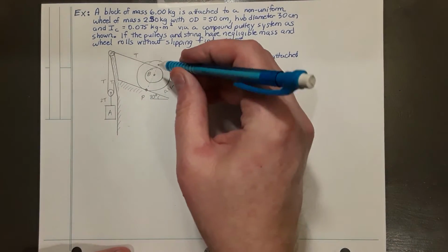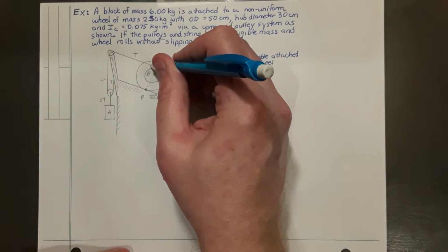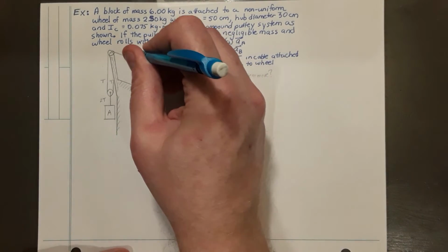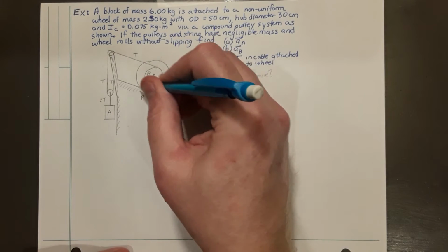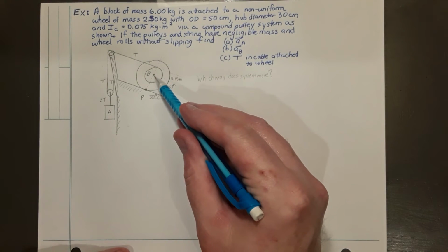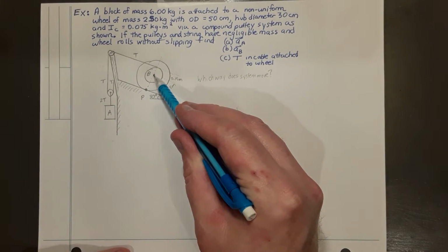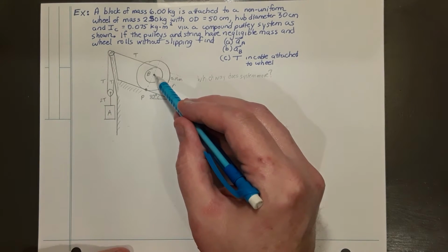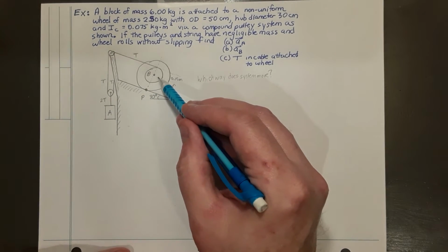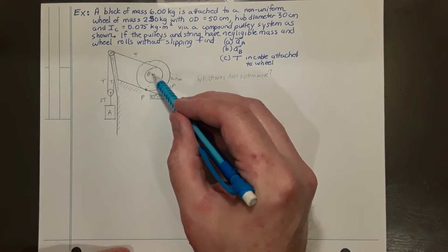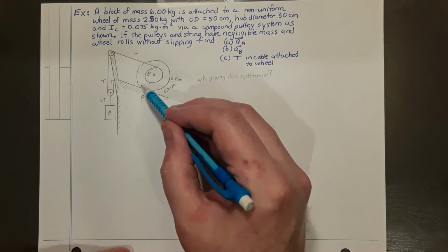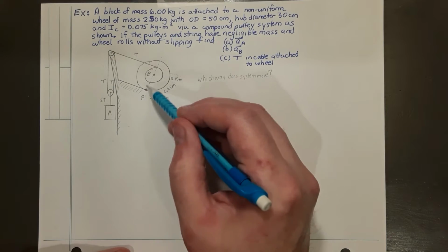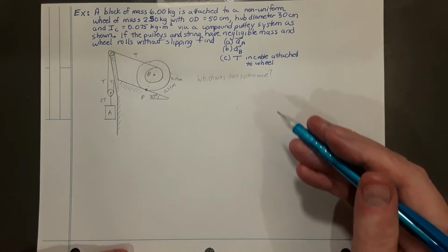On the wheel, there are 2 competing loads. The tension is trying to pull the wheel up the incline and give it a counterclockwise spin. The weight vector acts at the centroid of this wheel, point B, straight down. If you resolve it into its components, there will be a component along the incline which is going to cause around point P a clockwise moment.